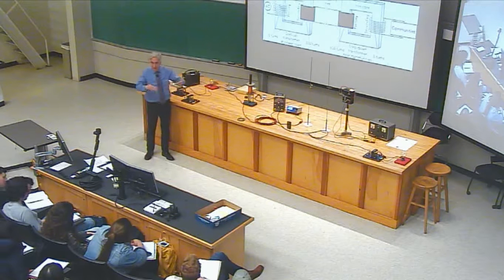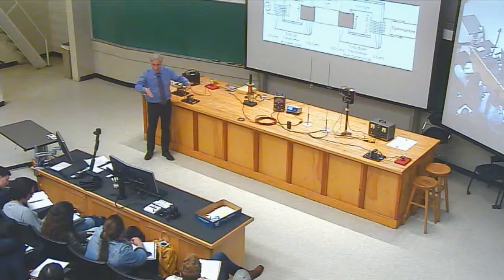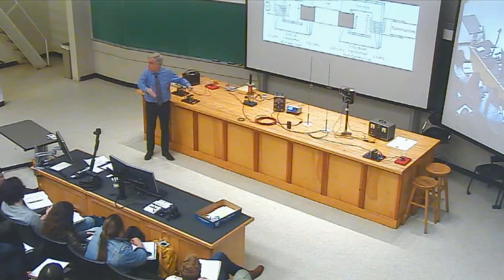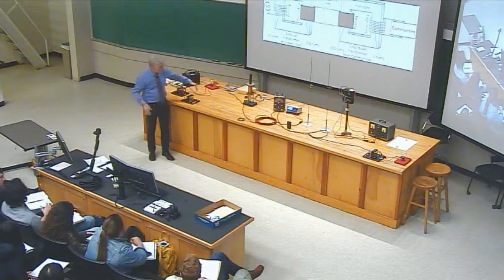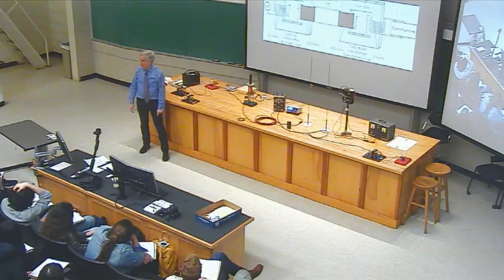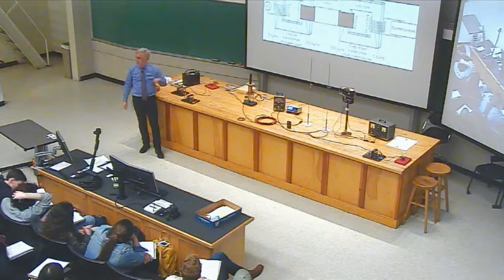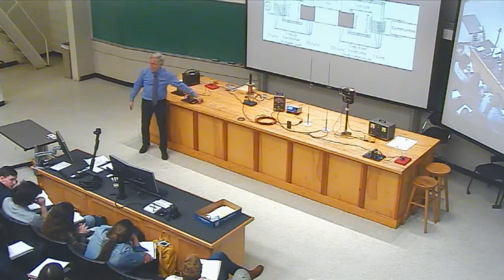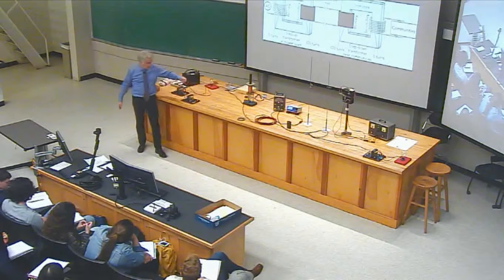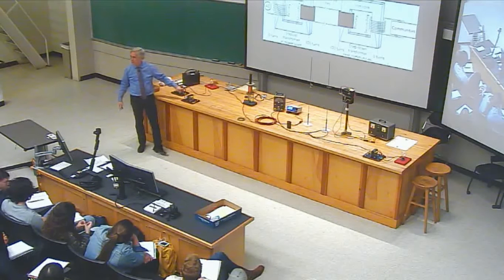And the voltage difference between entry and exit isn't 12 volts anymore. It's like 120 volts, much bigger. So each charge that goes through, wow, comes out with 10 times as much energy as the charges that dropped off the power. So you only need 1/10 as many charges per second going through these wires, to carry all the power that arrives through these wires.